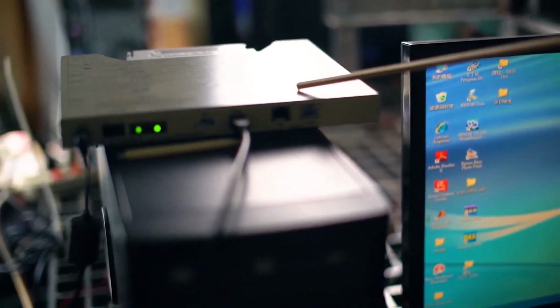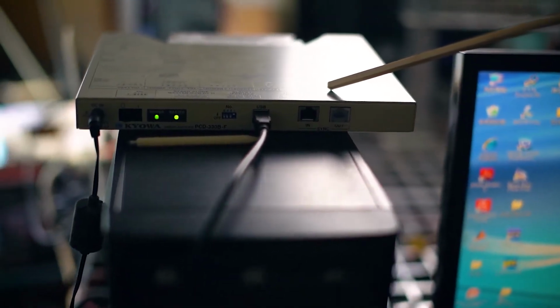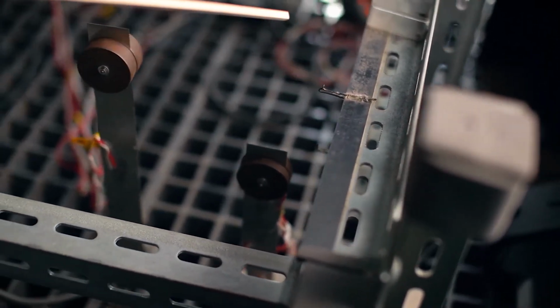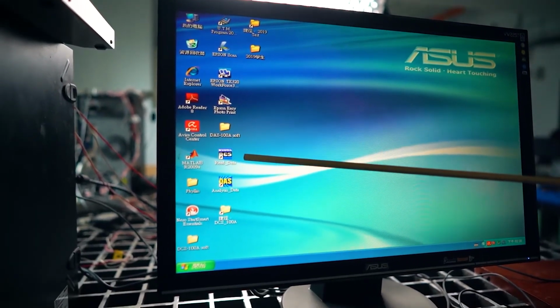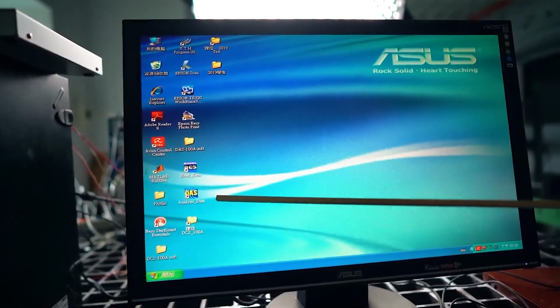This is the data logger of the strain gauge. It can read data from the gauge. Use this steel ruler to measure the free end of the steel plate. Use the programs Read Data and Analyze Data on the computer for this experiment.